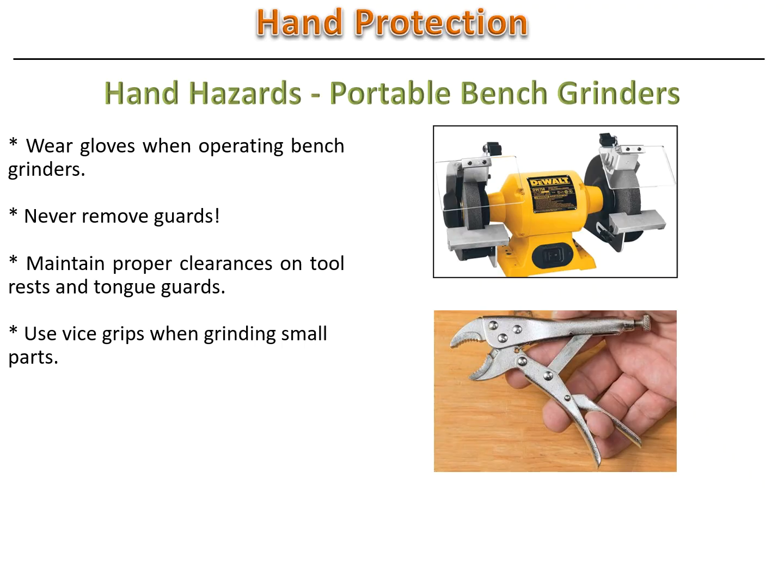Hand hazards, portable bench grinders. Wear gloves when operating bench grinders. Never remove guards. Maintain proper clearances on tool rests and tongue guards. Use vice grips when grinding small parts.